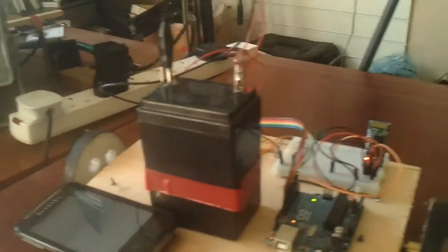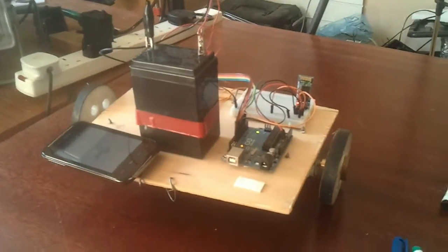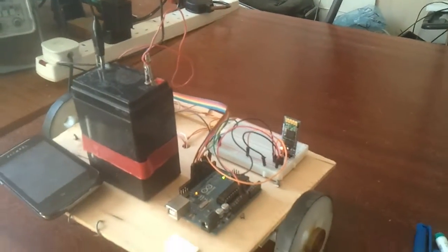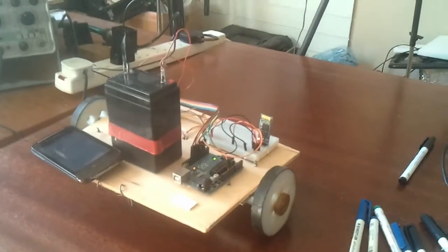I'll click the menu and you'll hear a noise. That noise is the pulse width modulation coming on the robot. I deliberately haven't suppressed that with capacitors because, for reasons which will become clear, it's very useful to be able to hear that. You can sort of get a sense of what the system's about to do. So I'll just nudge it up a bit further, and the robot moves forwards. Now I'll move it backwards.